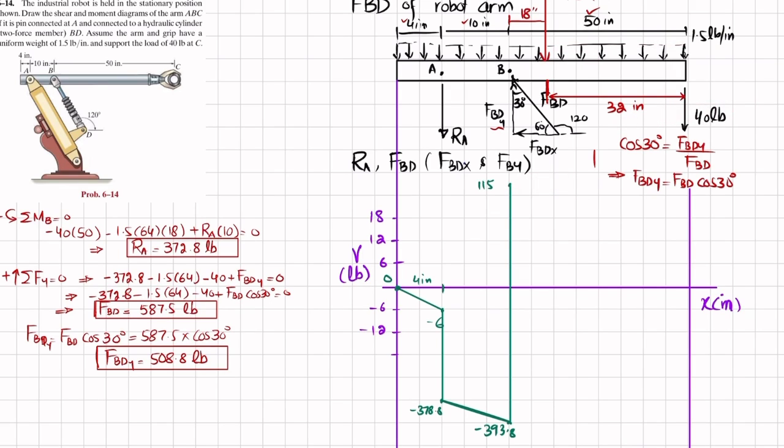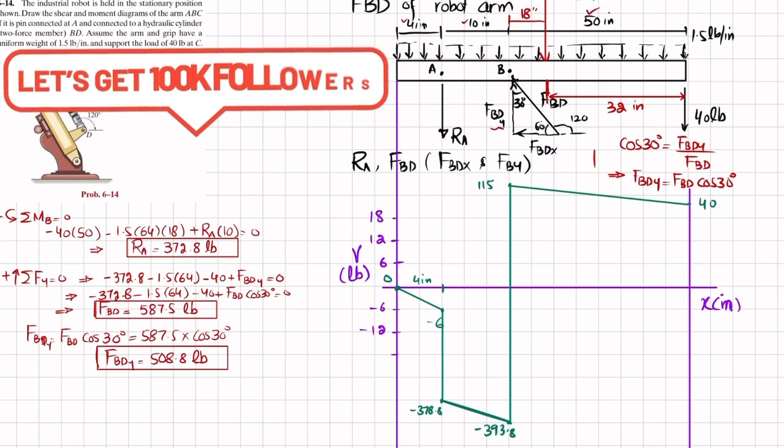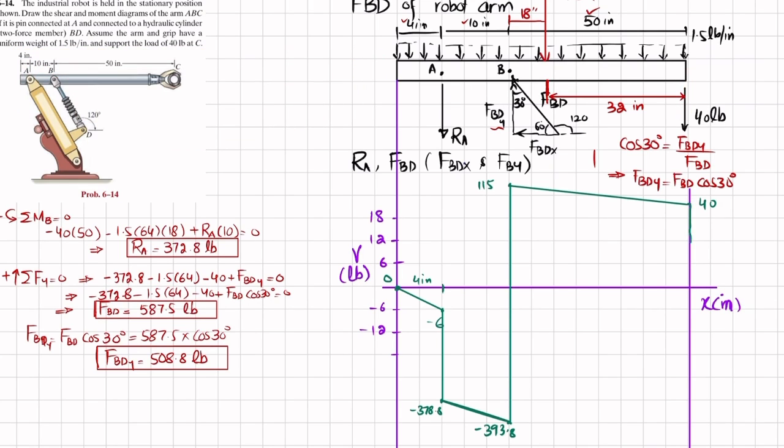So at 40, you can draw it using a straight line and slope is decreasing. Now at the end you can see that you have minus 40 which will bring it to 0. Clear? And this will be like this. So this is your shear force diagram.